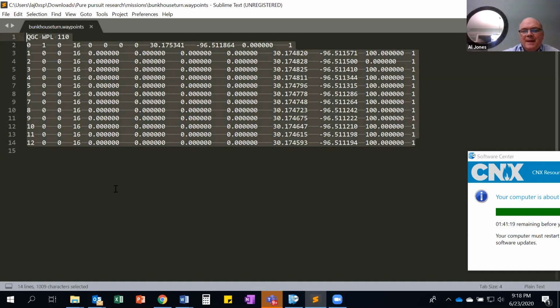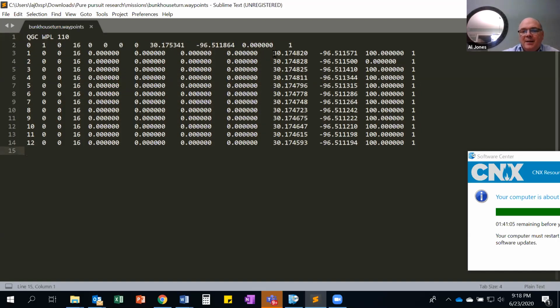If you go to a piece of open source software called Mission Planner and you point and click on a map and you save the waypoints, this is ultimately the text file that you get. It's not very complicated. Here's the heart of it, a lat long with, I think these were probably distances, I've forgotten. And if we're not at that point, that's cool.